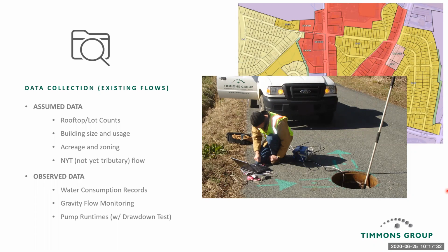There's also gravity flow monitoring, which means we'll take a gravity flow meter and put it into a gravity collection network, and over a period of 2 weeks, 2 months, we will monitor in almost real time what flow rate is moving through that pipe.